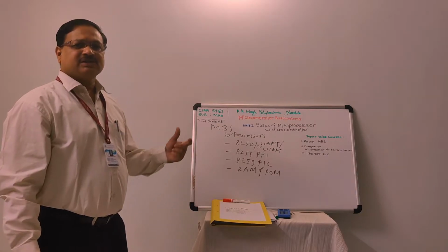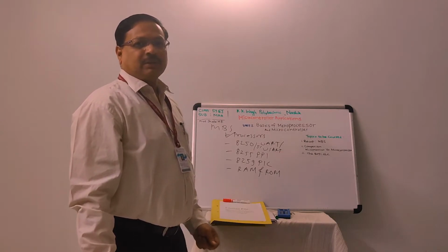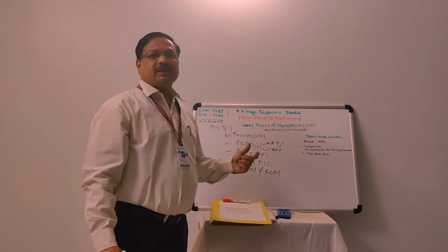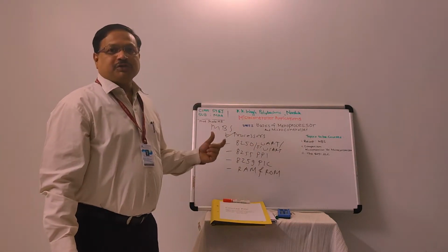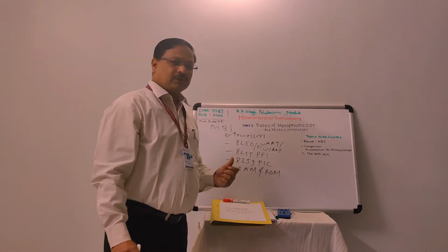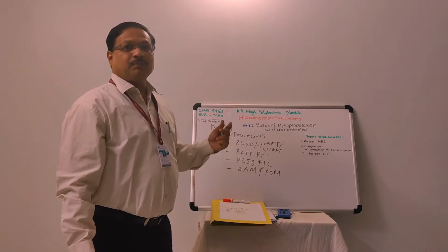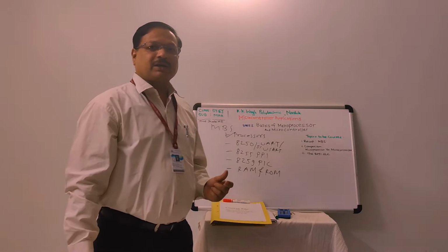When we say microcontroller, you will find that many of these features are available on chip. A microcontroller provides a single chip solution. Say for example, a microcontroller has an on-chip full duplex serial port. Also, it has on-chip 4 parallel ports used for parallel data transfer.